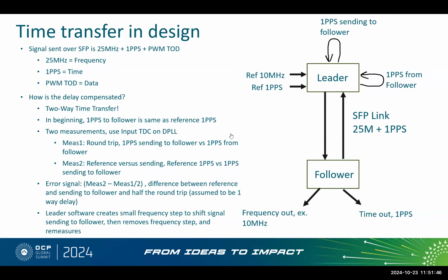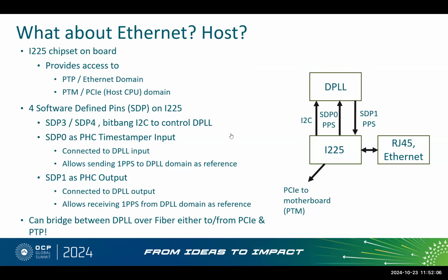So I can see almost using this scheme just to send 1 PPS and using the so-called out of band, which is the Ethernet, to send all the other information that you want, including PTP. If you can get the two 1 PPSs aligned, you just need a message to say, what is the time at the 1 PPS? And that you can do pretty well with PTP, NTP, semaphores, whatever.